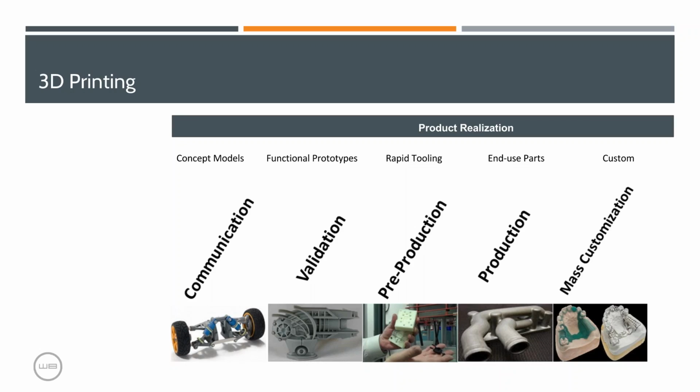The next one, which is one that's actually caused a lot of buzz recently, is since we've been able to develop a wider portfolio of materials, specifically high temperature materials, now pre-production is possible, right? So you can actually injection mold parts using 3D printed molds. So this is something that helps bridge the gap significantly when we run up with a lot of situations where we're designing something for a customer or even trying to sell a printer into a customer.